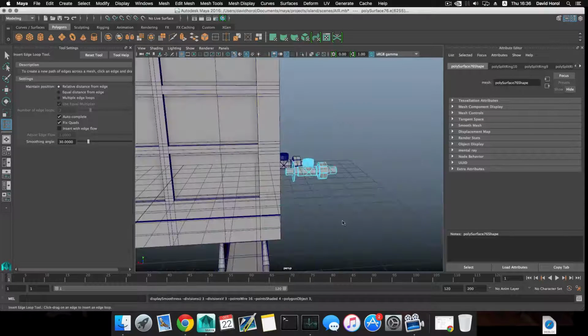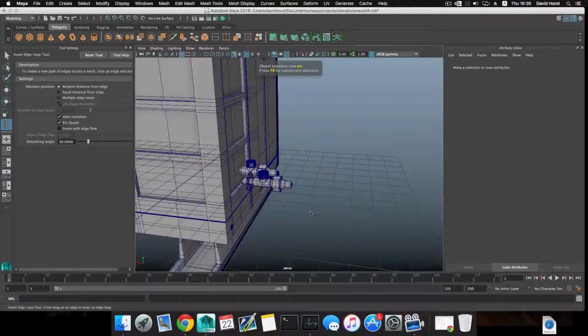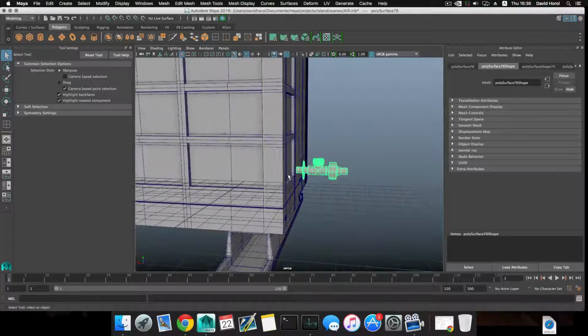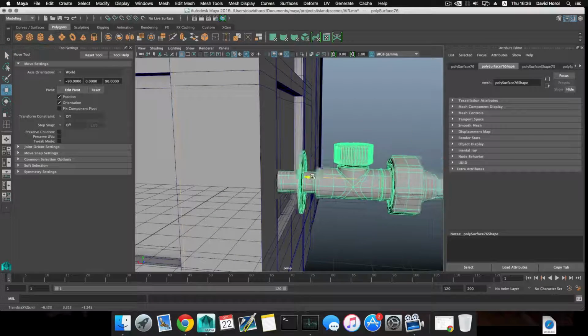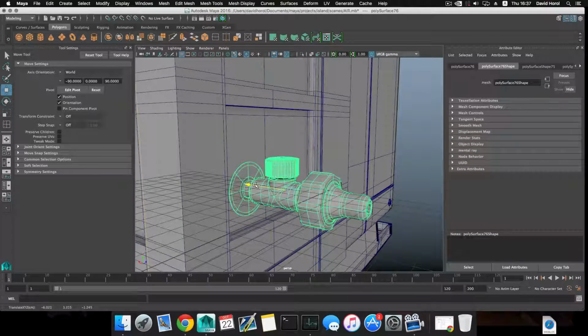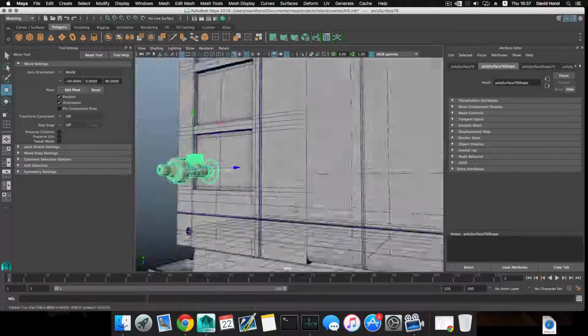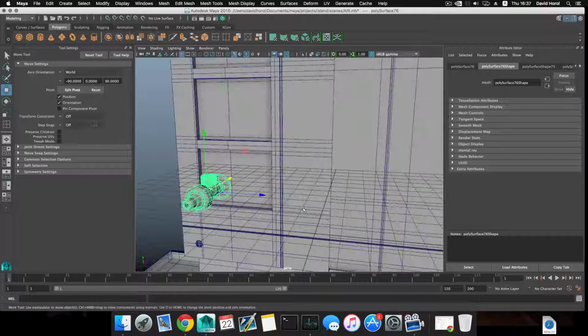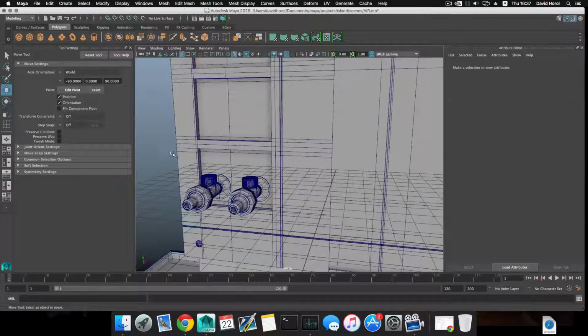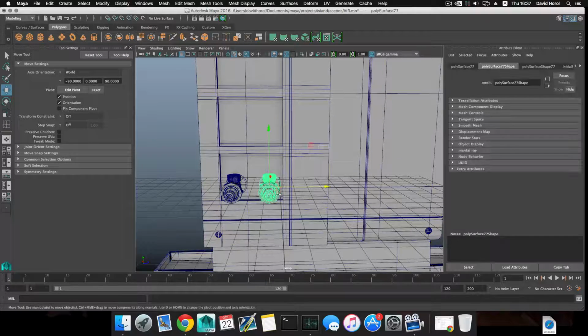All right, press 3, press F8, and now you will understand why I've done this. So I'm going to stick this back. Make sure it's not inserted, just there. Control D, duplicate this, move it towards here. Here you go. We have these two nice pipes.